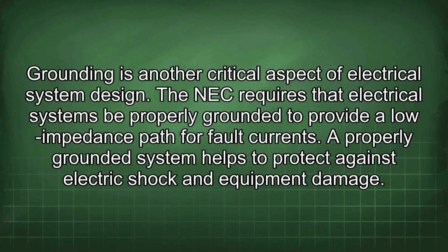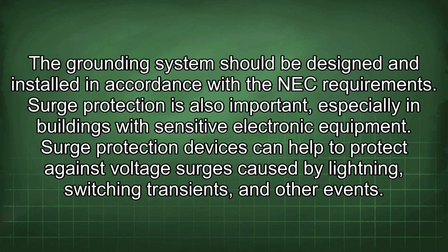Grounding is another critical aspect of electrical system design. The NEC requires that electrical systems be properly grounded to provide a low impedance path for fault currents. A properly grounded system helps to protect against electric shock and equipment damage. The grounding system should be designed and installed in accordance with the NEC requirements.